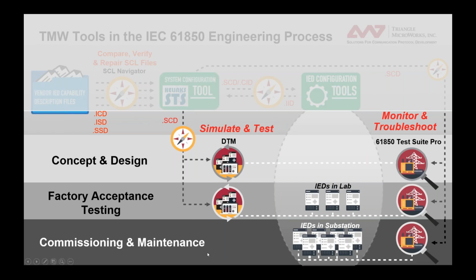In the final phase, the commissioning and maintenance phase, DTM is no longer simulating anything. Test Suite Pro is then brought into the substation and verifies that everything is working properly out in the field, using the same tests we designed in the conceptual phase.